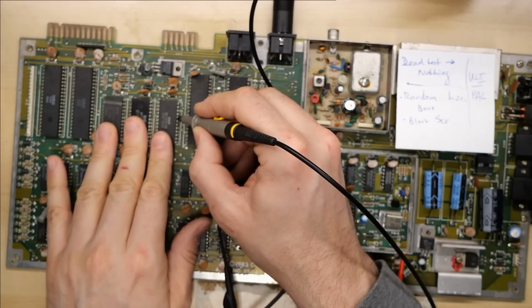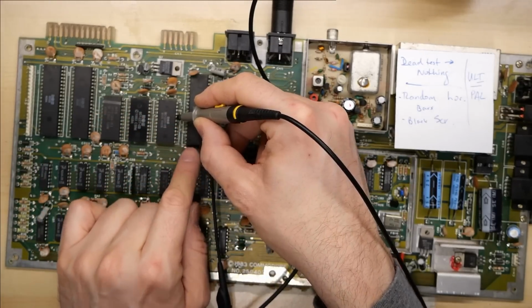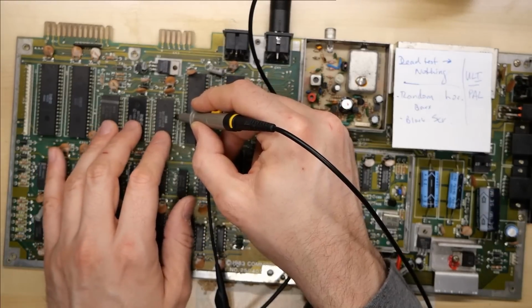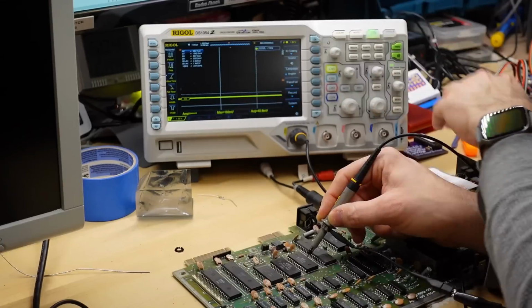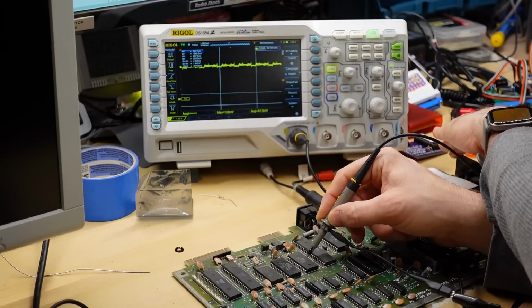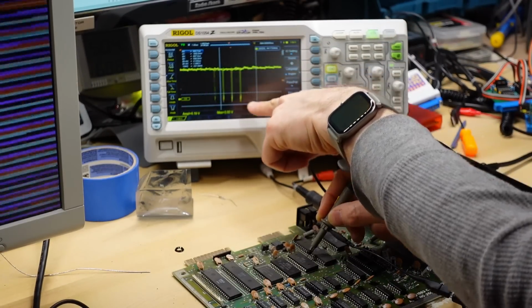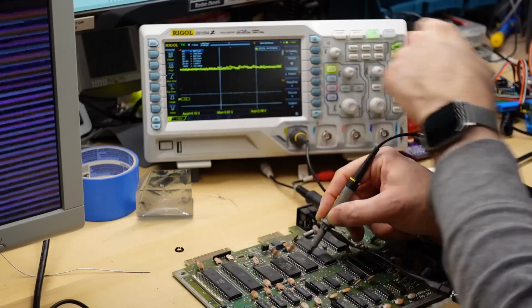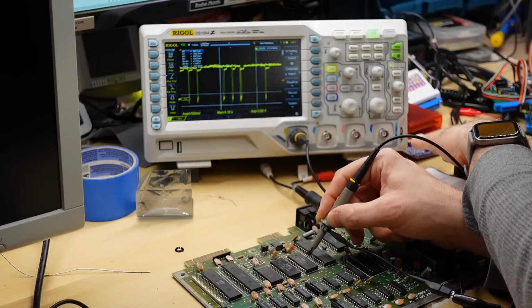Okay, so on the 3 ROM chips here, pin 20 is the chip select line on all 3 of these, and that is driven directly from the PLA, which is under my hand. So when I turn on the computer, I am on pin 20 on the character ROM. You'll see the way the chip select lines should look. See, it kind of went up, and then there are these little drops down. Oh, look at those lines that are happening. That is because this chip is being selected on and off by the PLA. Okay, see that? That's normal.